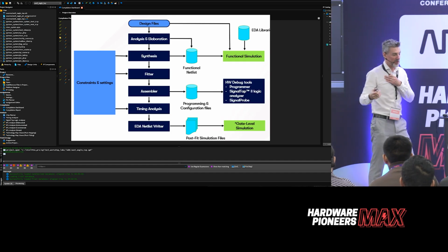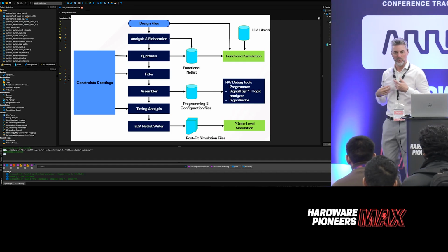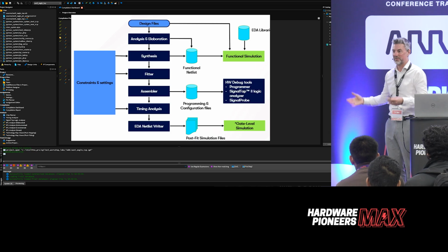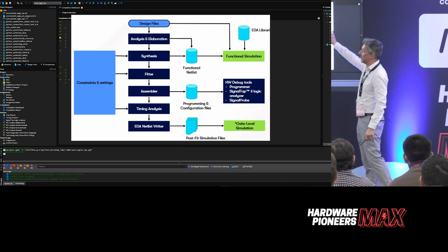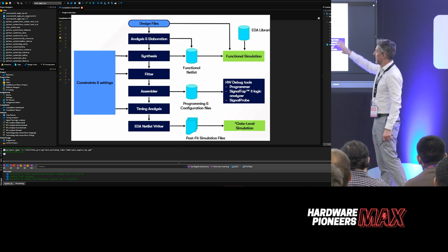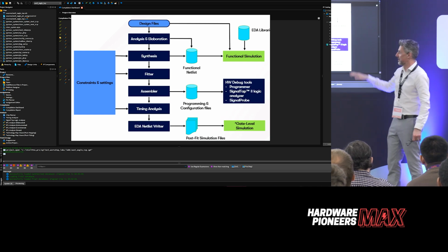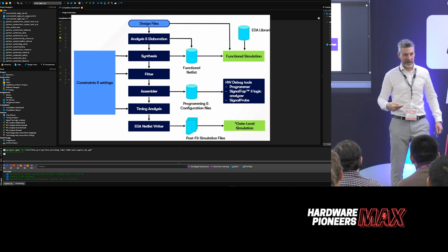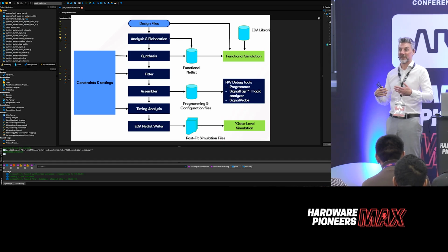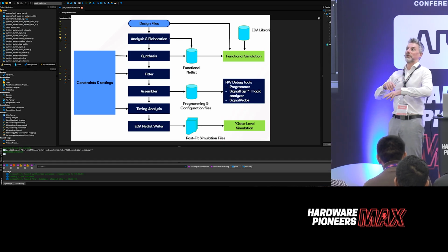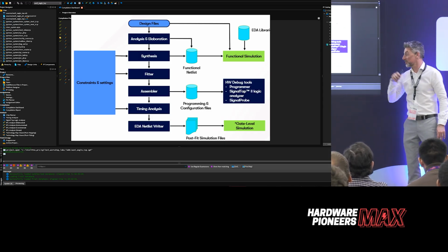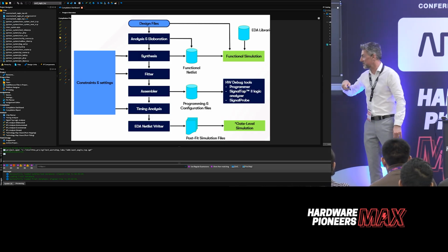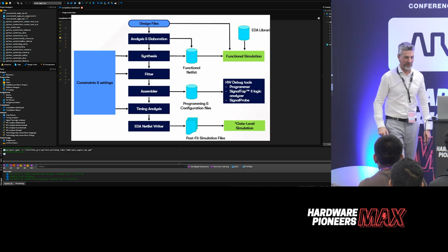So most people use what I would call ModelSim. It's now called Questa Sim, but basically it's an industry standard simulator. There's others available. You can do it at the functional stage, just built on your code alone, or you can do, this is for the brave, a full gate level simulation where it's cycle accurate. It's taking the output of the tool, the full netlist of the FPGA, and you can simulate at that level as well. We have some customers who have to do that for certain applications. It takes forever to run, but you can do it.